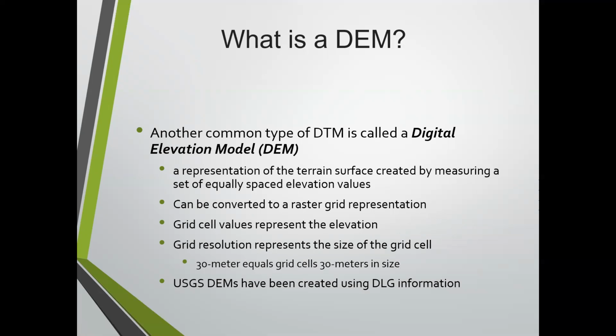So you have different levels of information that you can generate to or from. You can also take contour map data, contours that have elevation on them, and dump them into a program like Civil 3D and generate a TIN from that. That actually gives pretty good data, but even that data does not have break line data. You can add it, but it doesn't have it per se.